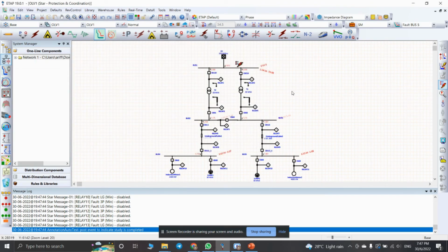Okay, the sequence of relay operation at each bus for the power system network has been completed. As the result, our simulation of this power system network worked almost precisely. We obtained the accurate maximum current at each feeder, the correct fault current at each bus, the correct transformer current, also the time dial and pickup time setting, time current coordination curve, and lastly, the sequence of relay operation at each bus. All of our parameters could be justified with some evidence and explanation.